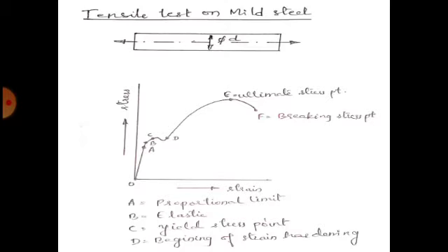If the specimen is loaded beyond the elastic limit, the strain increases more quickly than the stress. Sudden elongation takes place without appreciable increase in the load. This phenomenon is called yielding. The stress corresponding to point C is called yield stress. After B point, the material shows the plastic behavior. From point C to D is perfectly plastic behavior of material. If the load on the specimen is removed, then the elongation from point B to D will not disappear but will remain as a permanent set.